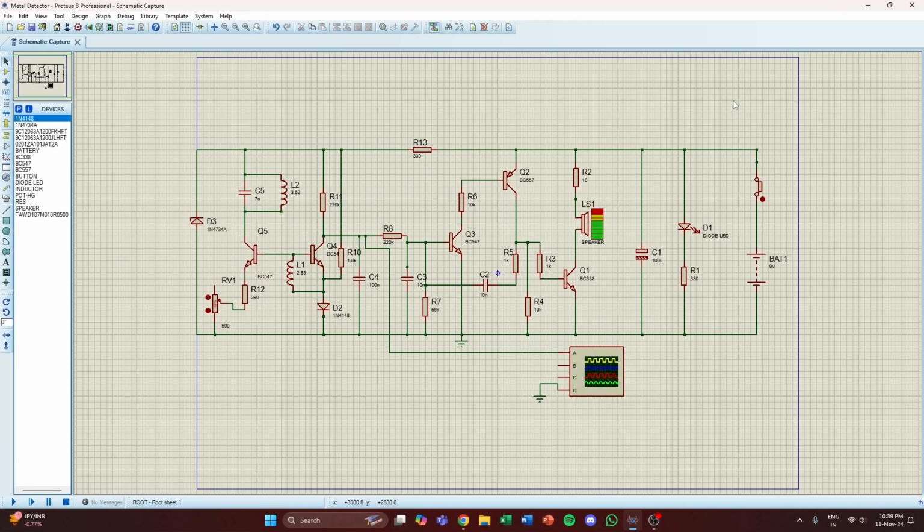So now we start with our circuit. The first block is a feedback oscillator consisting of the first transistor Q1, the capacitor C1, the inductor L2 and the inductor L1. The first transistor is turned on via the diode in the emitter of the second transistor, Q2. This diode receives its turn-on bias from the 1K8 resistor. The resistance of the receiving coil is very small, and the base of the first transistor sees a turn-on voltage from the voltage across the diode.